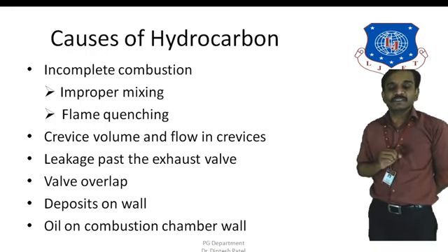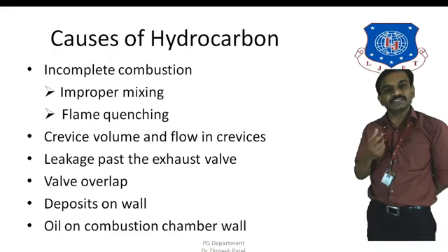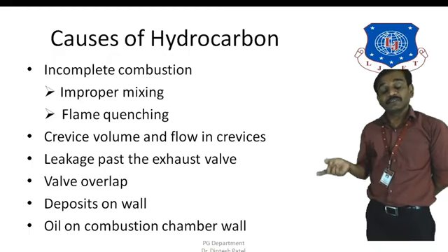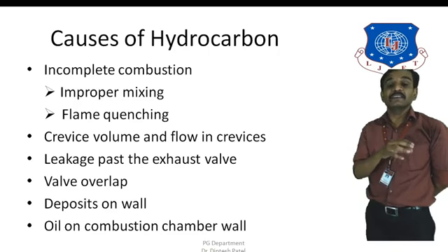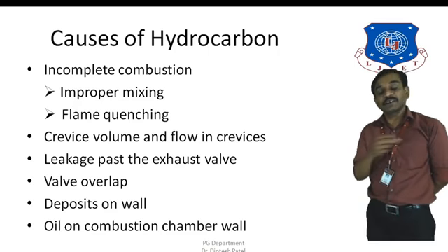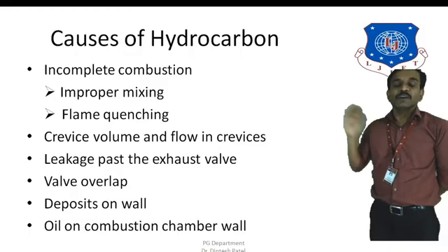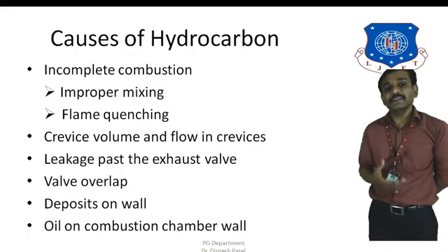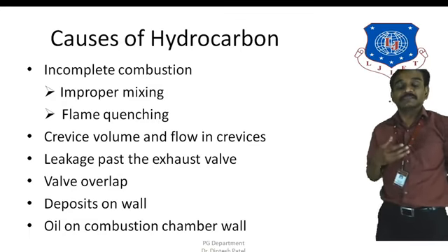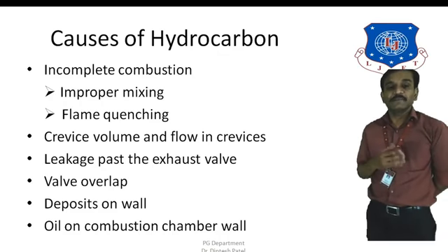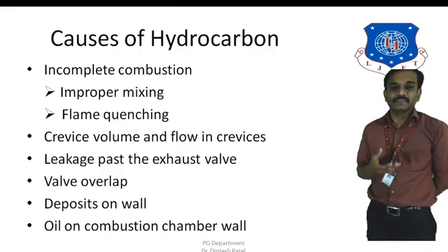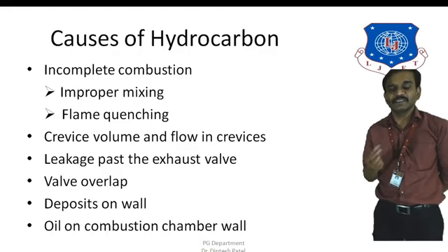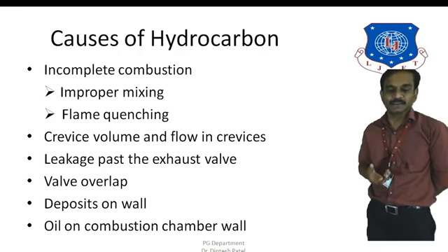Now, during the expansion stroke, obviously the pressure inside the combustion chamber is reduced, and at that time the pressure inside the crevice volume is higher compared to the surrounding pressure, and therefore the fuel that remains in the crevice volume would run out and flow back into the combustion chamber during the expansion. So crevice volume would also create some unreacted fuel. Furthermore, this issue, the unburned fuel in crevice volume, is highest during cold combustion, because the ring would expand after it reaches a certain temperature.